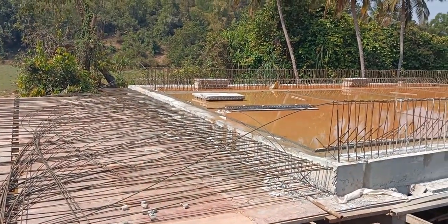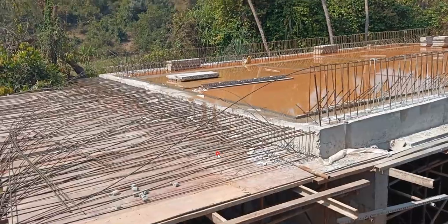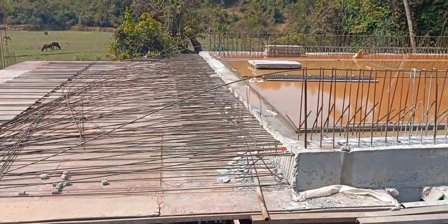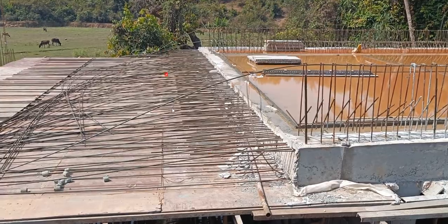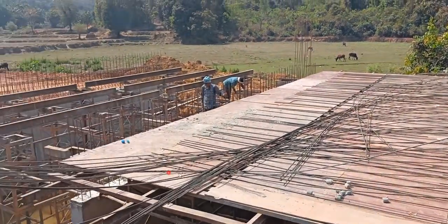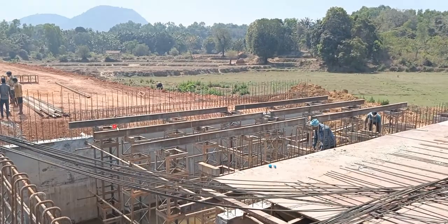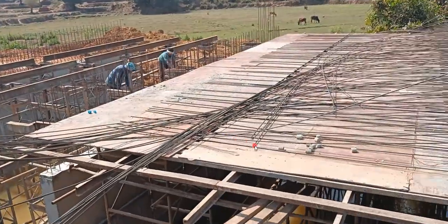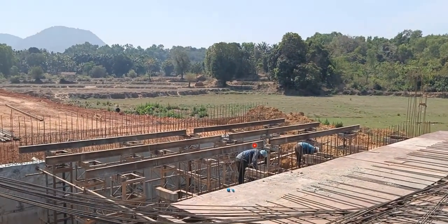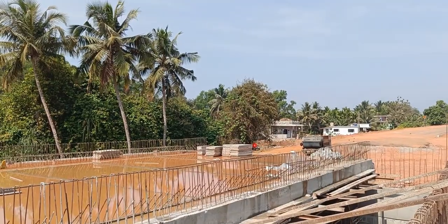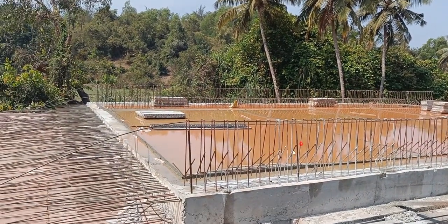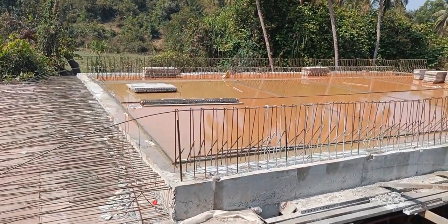So again here very simple, we'll be getting a top mesh, like for the combined footing or the raft foundation, how we do, no, the same thing we'll be doing here. Top mat, top vertical or top horizontal, in the bottom vertical and bottom horizontal, in this way, and then you will be keeping a chair, and based on that the entire thing will be done. Okay, simple. So on this slab already the curing is happening, and this portion is left out, that we'll try to do.